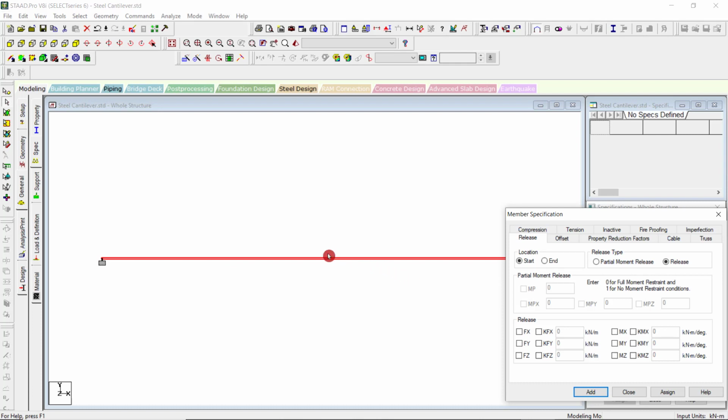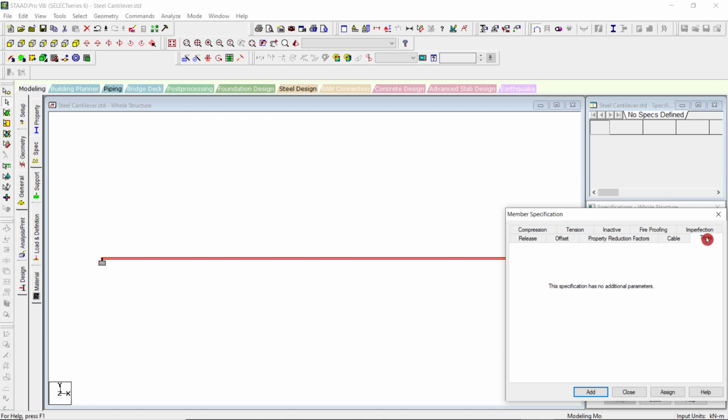This is a truss element. When we have to design for a truss element, all the beams should be selected and given only the truss option, so that all the members take either compression or tension. If you don't switch it on for truss configuration, then it will take bending also, which will give you error results. Then cable analysis.